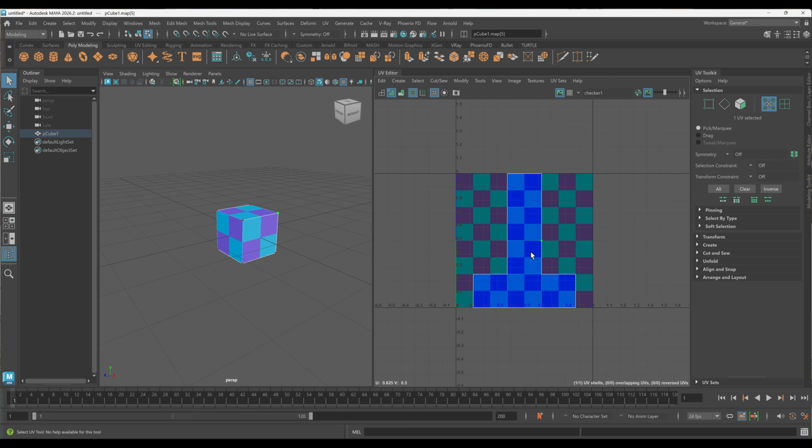Although it is a single vertex on the 3D model, it can be split into multiple UVs when the model is unfolded. As a result, one vertex may correspond to multiple UV points, each of which can be selected and edited independently. When you move the UVs, the sampled area of the texture changes as well, causing the texture to appear distorted. In other words, UVs are coordinates that determine which part of a texture is applied to the model.